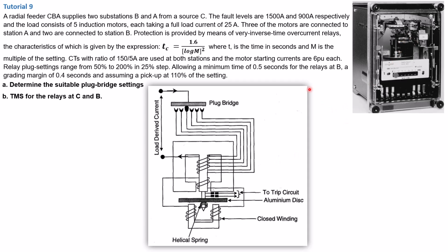Now, this is important for relay coordination, because if that time is not taken into account and you've got a bunch of IDMT relays on your network, each one of them might start tripping at the same time, and all of a sudden all the busbars are going to be out of power. So they have to allow coordination. One has to trip after the other based on the level of the fault or whether the fault hasn't been cleared yet.